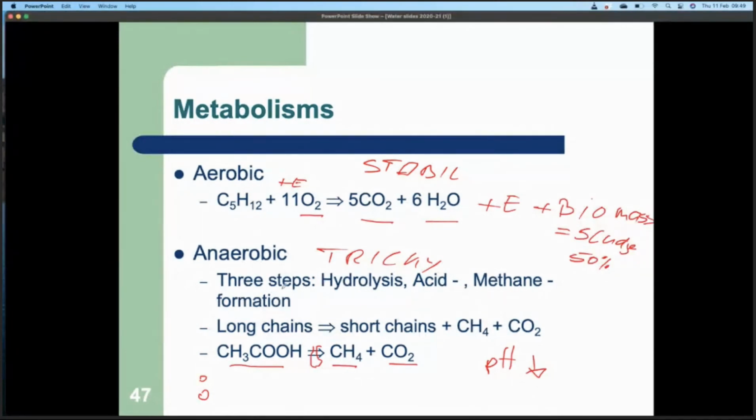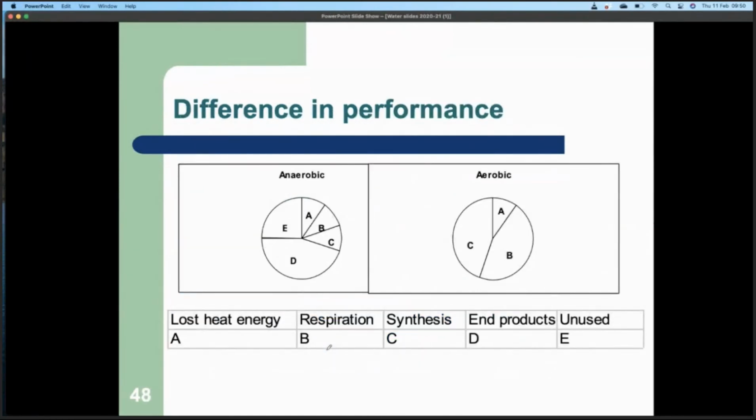And as an aside, that's why it is used in sludge treatment, because with the sludge, you control the sludge, you have a big tank of sludge, and you feed that constantly into anaerobic digestion. There's no change in consistency or substance because you're taking it from a big buffer tank, and the happy anaerobic bacteria will reduce the BOD that comes from secondary sludge very easily and turn it into methane. Anyway, I'm putting a lot of concepts together in one here. So let's maybe step back a little bit and go over this same stuff in a different form.